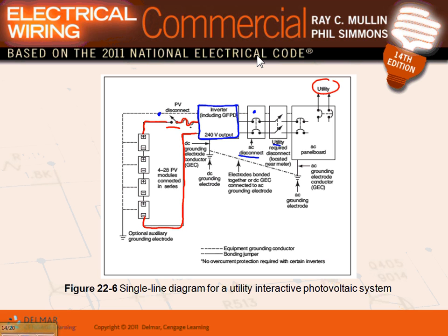You need to create a grounding electrode system here. This is for your grid. Also, you have to have a grounding electrode system for your inverter. You have to bond and ground your inverter right here, bring it to the ground, and also you have to tie the 2 grounding electrode systems together. Can you guys see that? And your panels most likely will be number 6 copper, coming all the way for grounding all these panels on the roof or somewhere else and going to Mother Earth, tying them to Mother Earth.